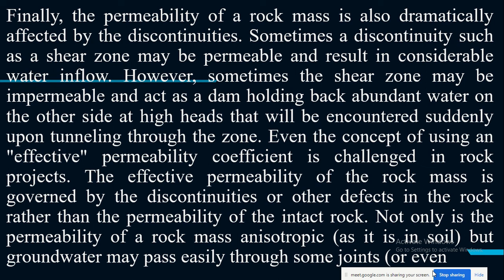There is no agreement on how to define permeability of the rock mass, because if one discontinuity is just a fraction of a millimeter, and another opening is 2 millimeters wide and another 5 millimeters wide, they will allow different amounts of water to pass through.